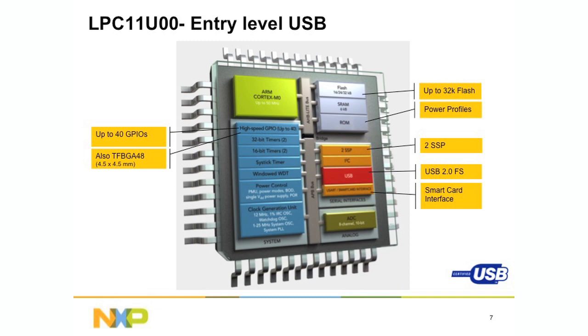This part has been certified by USB.org, which basically means that if you go to USB.org and type in LPC11U14, you should see this listed on the website. The next version of this has USB drivers in ROM, which makes it exciting, especially in situations where you have constraints on the code space. The ROM has drivers for HID, mass storage class, CDC, and you also have the option of doing your own custom class.